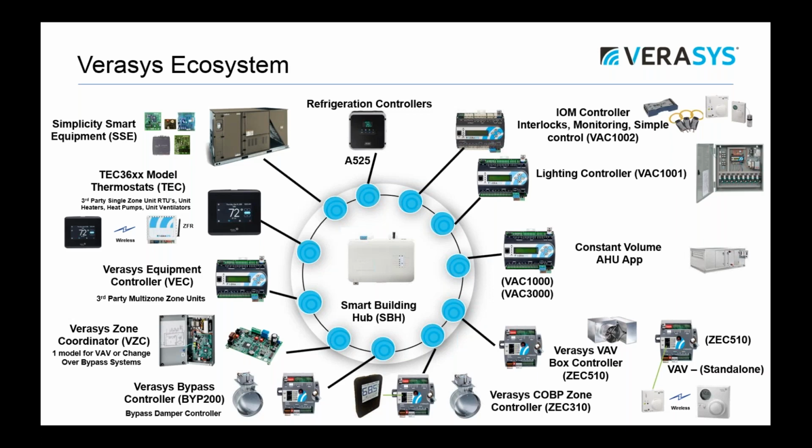Constant volume. I kind of mentioned controlling our rooftops, some heat pumps and rooftop units. Maybe they're too heat, too cool, but maybe you have a more complex air handler or rooftop, or maybe you have 4 heat, 4 cool, or mod heat, mod cool, or maybe you need to do dehumidification or humidification, or fan speed control.